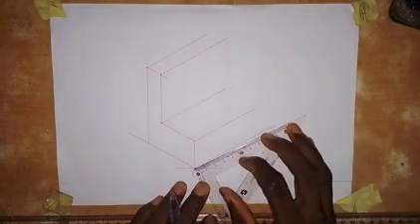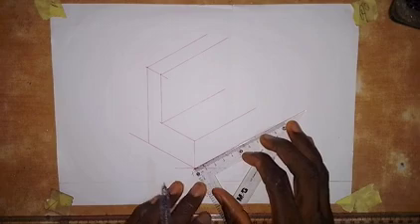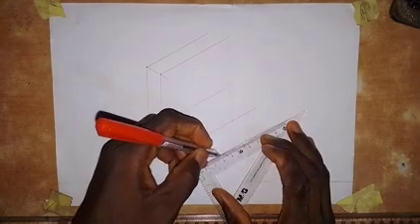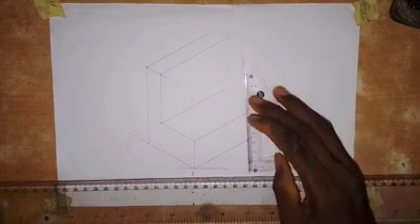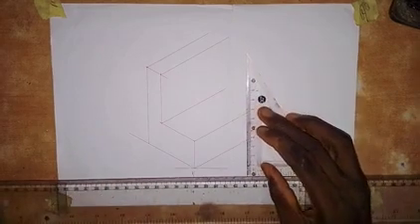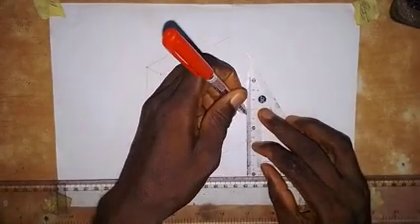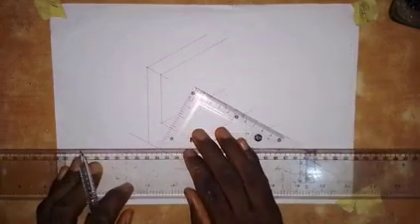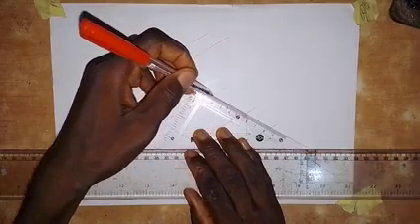All right, so the next thing that we are going to do: the length on this side is 60 millimeters. So we take a measurement of 60 millimeters from this point X here. This is 60. Let's get the midpoint. We need it, so we are still coming to that. Then, having taken that 60, you come to this point and draw a vertical line to touch this line. Then from this point, turn the set square like this and draw to this point. Let it touch this point.